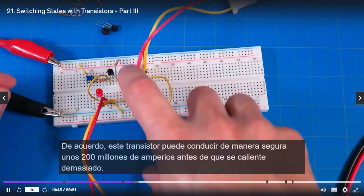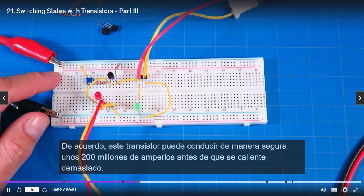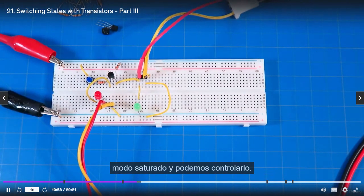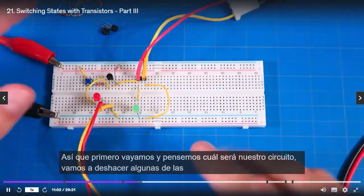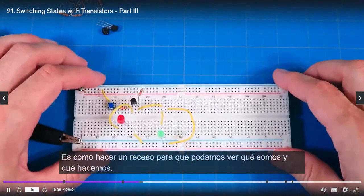All right, so this transistor can safely conduct about 200 milliamps before it just gets too hot. So if we have a load that's under 200 milliamps that we want to control, we can put this thing into saturated mode and we can control it. First, let's think about what our circuit is going to be. Let's just undo some of this stuff. We've got kind of a mess going on here, so let's do a reset so we can see what we're doing.